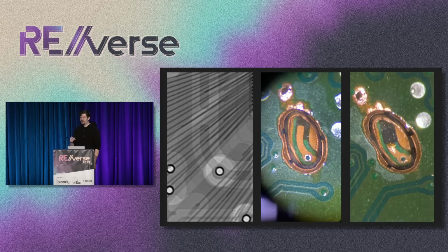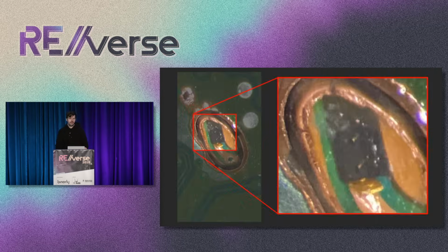And I started expanding upon it, and we have the X-rays on the left, and now we have the expanded hole. And this was just a throwaway chip on the right. I was just digging to see, okay, am I on the right track here? And so you're peeling back the layers, and on the far right, I ultimately peeled back part of that 3.3 ring. If we zoom in even further, I think I found them, right? I think I found these two little bond wires peeking out down there.